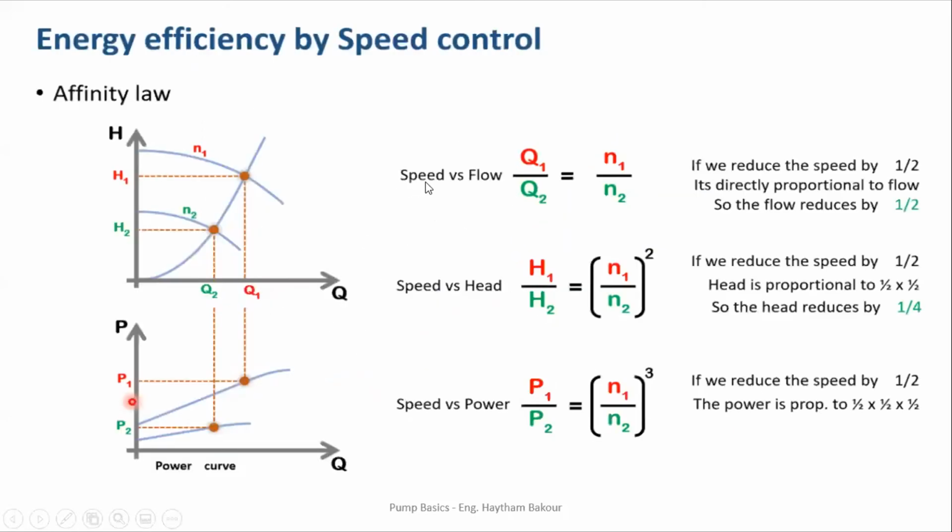We can see here in this picture the relation between N1 and N2, which is the speed we are changing, and how much it affects the pressure and the flow rate of water. So the speed would decrease and the value of the head. When we use the inverter, we need to study the case precisely, based on the timeline and the variety of the speed.